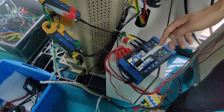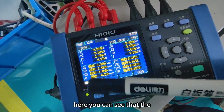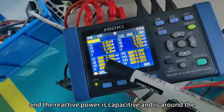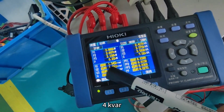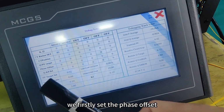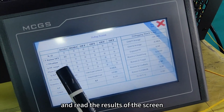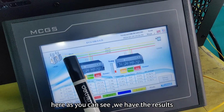Here you can see that the active power is around 6 kilowatts, and the reactive power is capacitive and around 4 kilowatts. Okay, and here on the SVG, we first set the phase offset to 0 and read the results on the screen. Here, as you can see, we have the results.